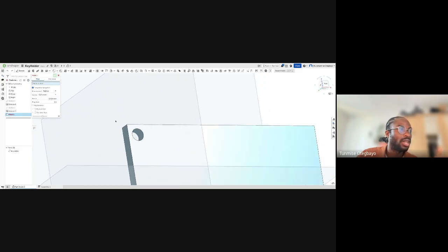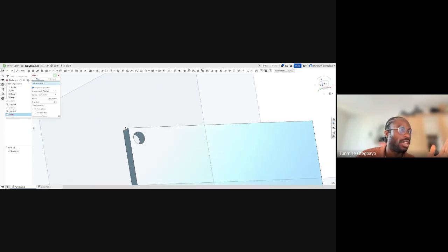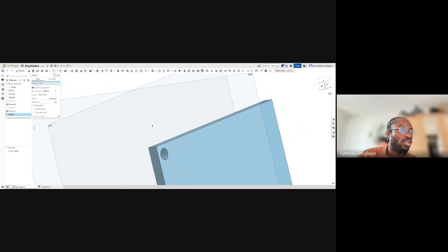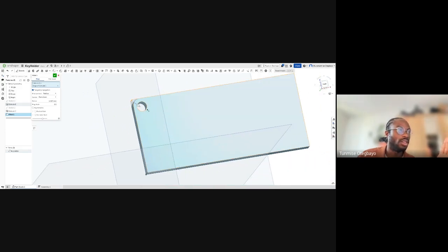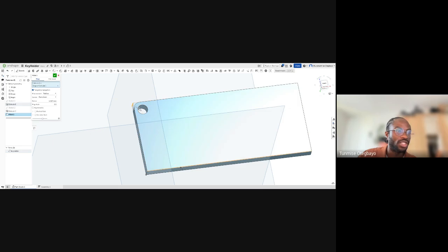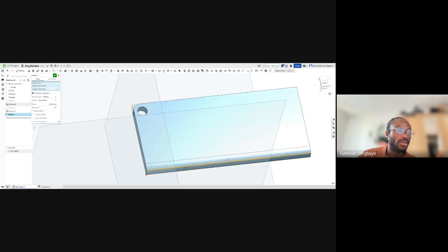It helps give a nice look. So imagine you have sharp edges and you want to make this a bit less sharp. You can grind this against a surface or sand it and it becomes a bit smooth and curved. You can turn this sharp edge into a curve. It will ask you what entities you want to fillet, and you want to do that to the edges. If you select this edge and pull, you can see it gives this very nice, round, cleaner look. And you can select whatever edges you want.